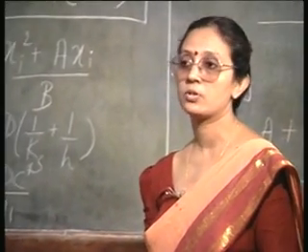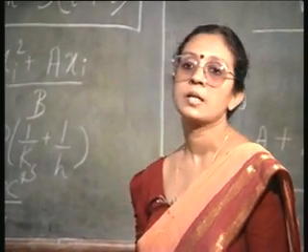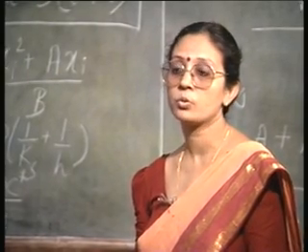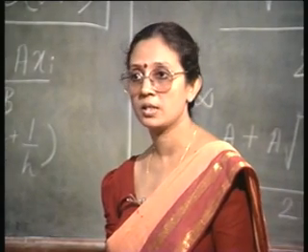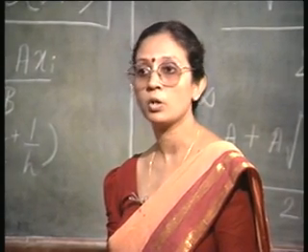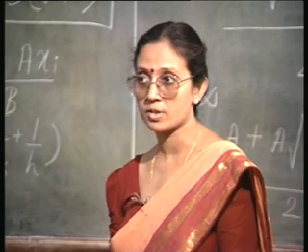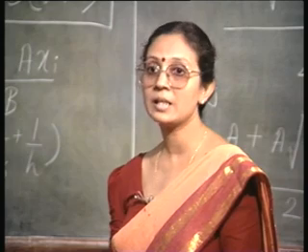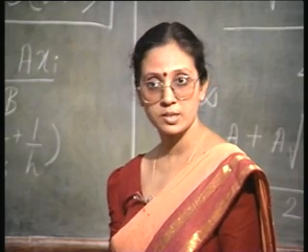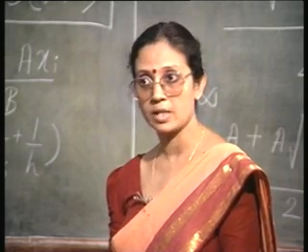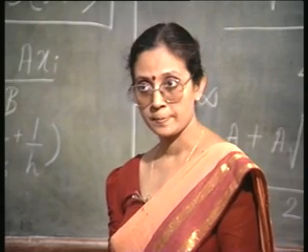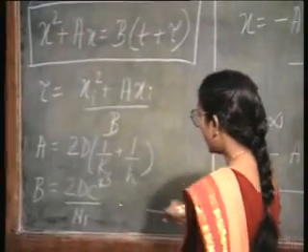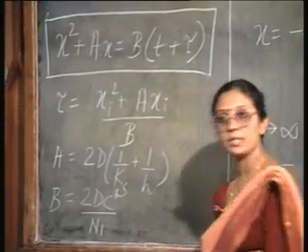Now, you know actually N1 is larger for wet oxidation, because in order to grow one molecule of silicon dioxide we needed 2 molecules of water. So, number of oxidant molecules per unit volume of oxide, this is actually double in case of wet oxidation than in case of dry oxidation. Remember? So, N1 for wet oxidation is actually larger.